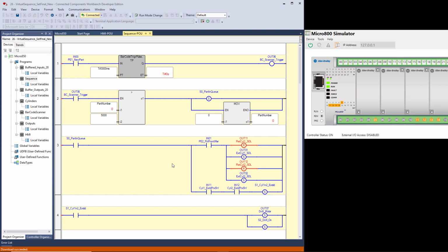There are other ways of going about it, but we're really not worried about that variation right now between single solenoid, double solenoid, spring return to center, detent, etc. Because you could use double solenoid valves that are detent, meaning if you energize one solenoid, it extends. You de-energize the solenoid and it stays right where it's at with the cylinder extended. And then when you energize the other solenoid, it pulls the spool over to that end and retracts the cylinder. You turn off that solenoid, but it stays retracted. In other words, it's detented.